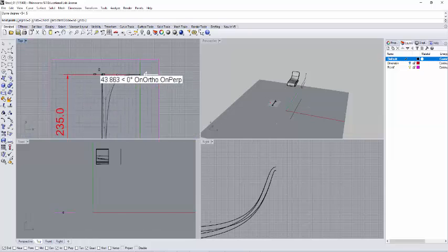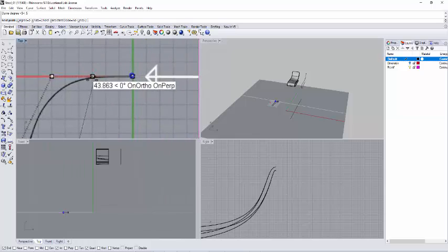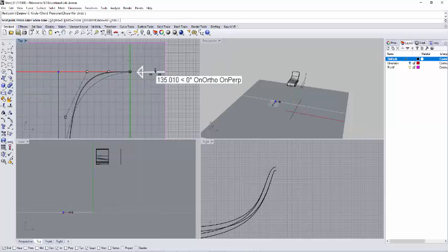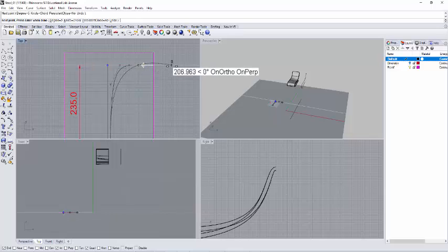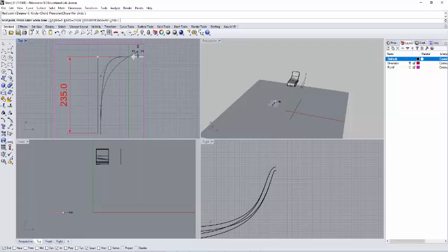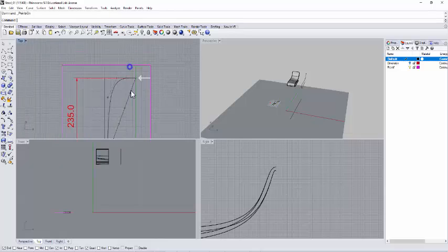Right now I'm using my smart track. So let's say I want here, and then I press shift. Make sure it's about the same, which is here. Click. Maybe my angle I want slightly here. Yeah, just drop first. And then I press my function F10. Okay, notice I got my 5 points here, right?